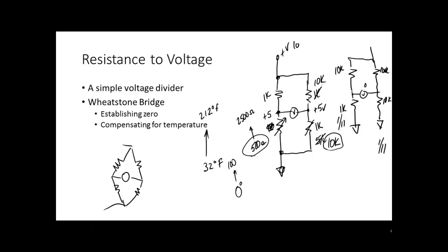The ratio, right. And you can figure out, so the low ratio would be your negative side, if it wasn't balanced. Your low ratio would be the negative side, and your high ratio would be the positive side, so you can calculate polarity too. You understand? So if I got over here and this had a ratio of 5 and this had a ratio of 10, then this meter would measure negative, if this was my negative side of my meter, right? You understand? So if this ratio is lower than that one, then we get a negative voltage. If this is higher than that one, we get a positive voltage.